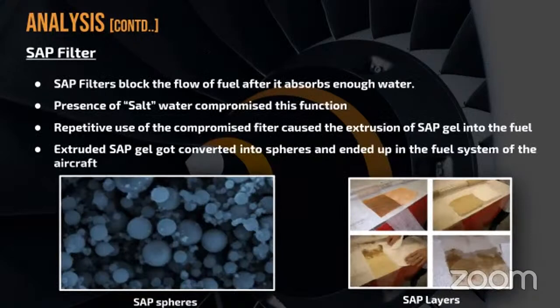The situation changes once you have salt content in water. With salt in the water, the gel could penetrate through the filter, forming spheres of varying sizes, and can reach various parts of the aircraft fuel system. Next slide.